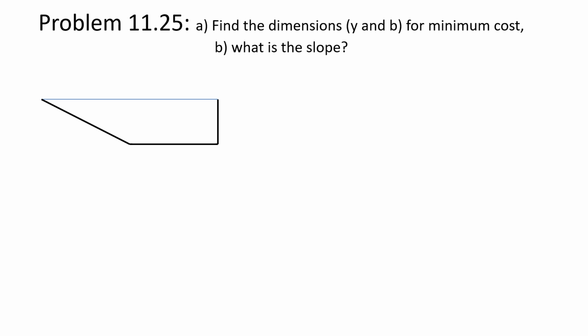One is the cost of the lining, so that is, like if you were going to put down some sort of a plastic or concrete, some sort of a lining to prevent water from being infiltrated into the soil. So there's the cost of the lining and the cost of the excavation. So you want to minimize the total cost that can accommodate the flow. How big should this channel be? And then what's the slope required to carry a certain amount of flow?